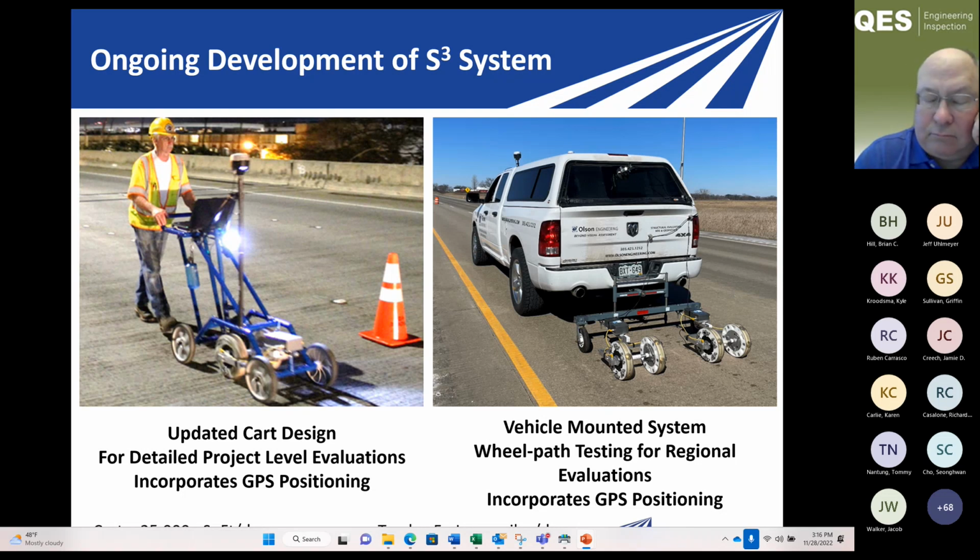That's a pretty conservative estimate with the cart. So we can usually knock out your run-of-the-mill bridge deck easily in a day with traffic control in one half and then flipping it to the other half. Even with the vehicle mounted system, because we're doing a mile an hour, we still need that traffic control.